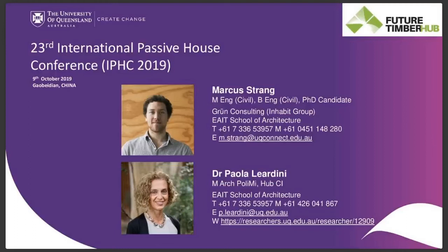I've now got a question from Matt Smith, and that was the vapor barrier of timber was discussed. Do you have any preliminary research on the glues used in CLT? Yeah, so I did do some simulation of that where I'm looking at the PUR, which is polyurethane glues, and that glue itself can be considered as a vapor barrier, so it does somehow limit some of the moisture that's coming through. But just to simplify the presentation, I just simulated it as a homogeneous material. But that is going to be some of my ongoing research.